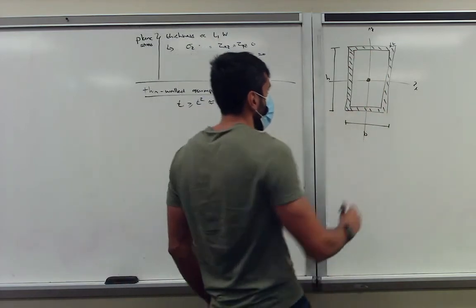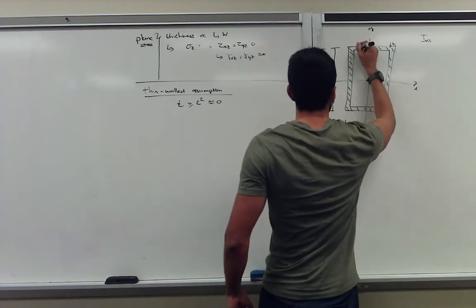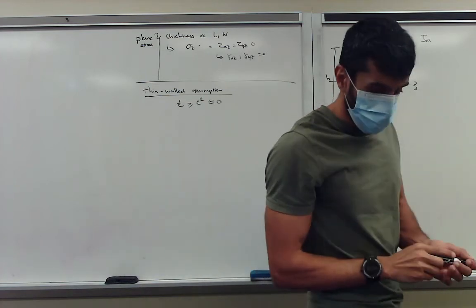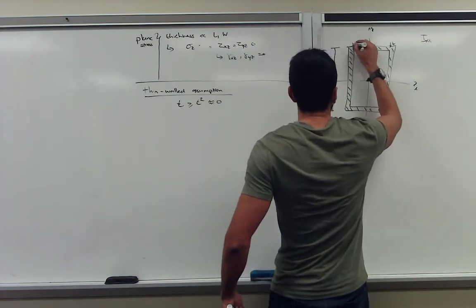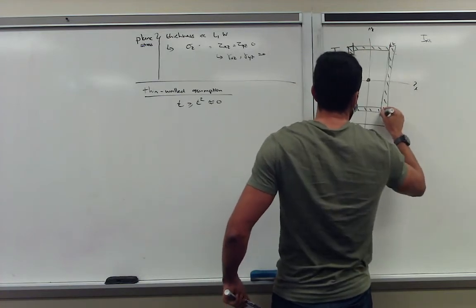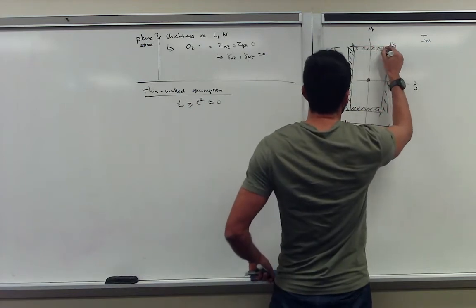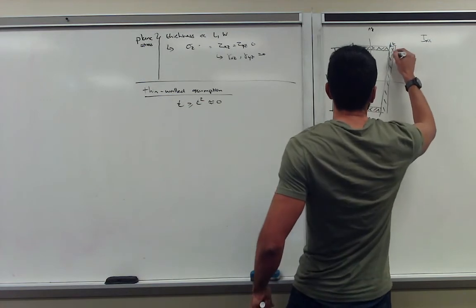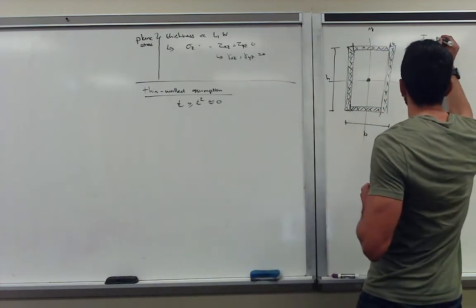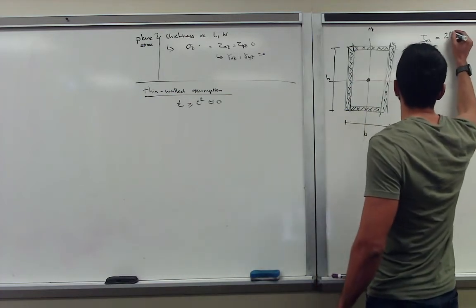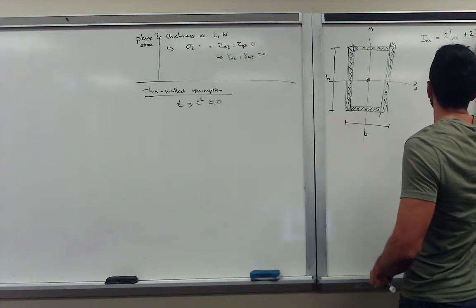Now, let's do the moment of inertia for this section. We said earlier that the moment of inertia is a contribution of the different segments. So we have a segment here, basically split up into 4 segments. Let's call this the green area, here we also have a green area, and then we have a purple area, and here, green here. So the moment of inertia of the cross section around x is twice the moment of inertia of the green section around x plus twice the moment of inertia of the purple section.